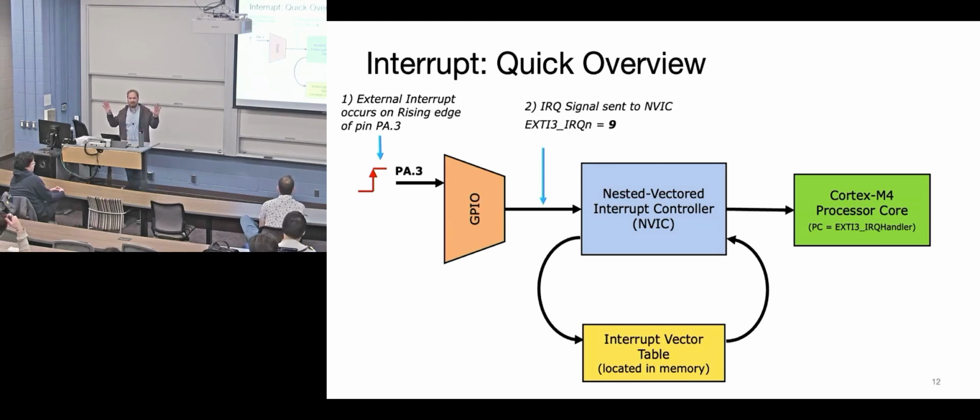When we look at STMs that you can buy, they don't all have the same memory amount. Some of them are small, some are big. So you don't know where the end of memory is. If you want to tell your core where the end of memory is, you can't have a static variable that goes across all hardware types. Does that make sense? Memory on an STM is going to be 120K, 256K, maybe even a meg if you're buying at the top end. So you don't know how big memory is. So when you boot up your core, you look at the 0th memory address, which tells you the top of your stack.